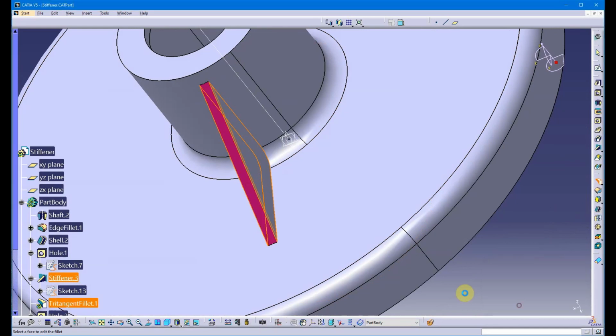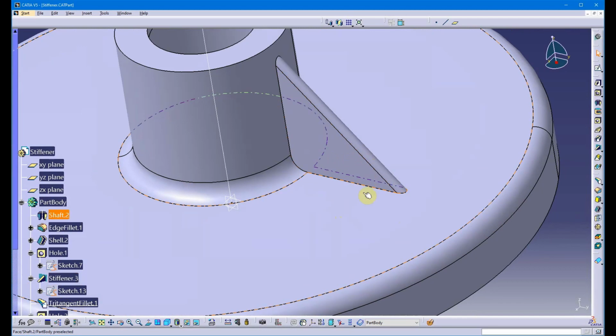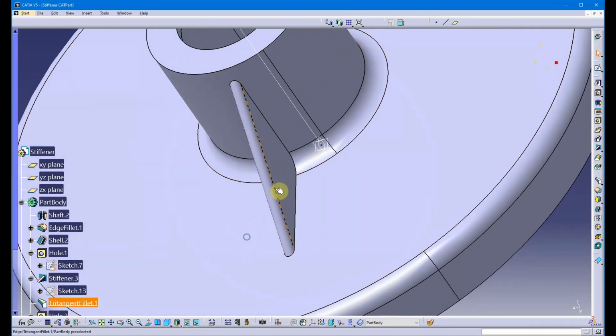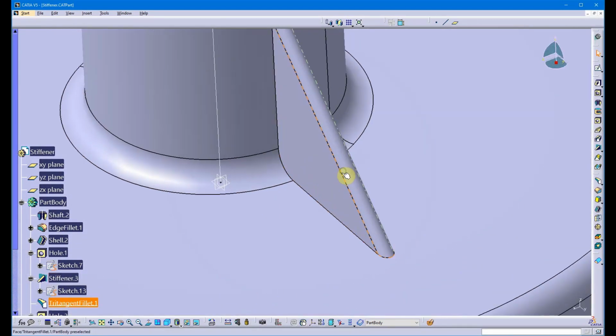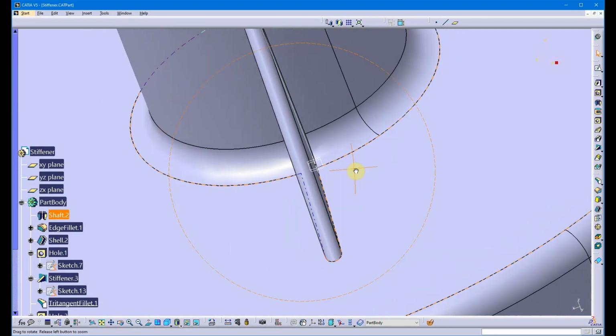It's an easier one to work with, so I'm going to blow through that one really quick. Now I've got three faces here, but the faces are tangent to each other. You've got three faces and a topological edge, meaning they're sharing a common edge, and those edges are tangent to each other. That was a tritangent, so I know they're tangent to each other.